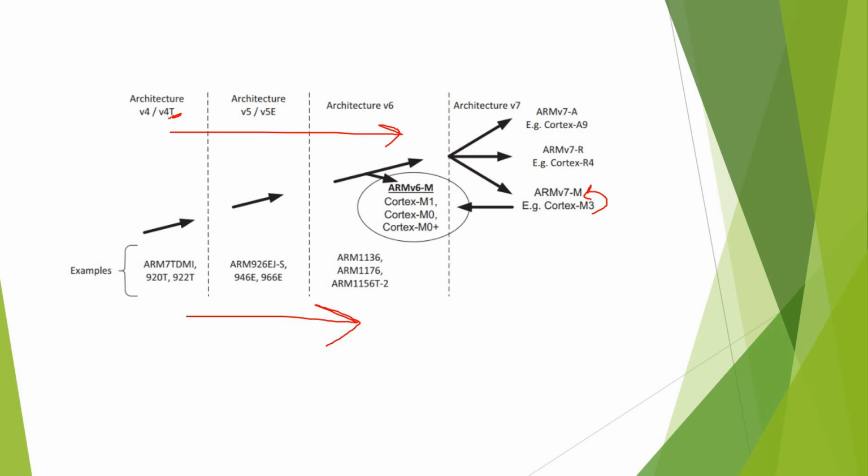This mix introduced new problems and challenges for ARM. One of the major problems was how the CPU will distinguish if the instruction will be 16-bit or 32-bit after doing a branch or jump. To solve this problem, ARM first introduced a new branch instruction called BX, or branch with exchange. Exchange means that the processor will have the capability, after a branch, to exchange its state to 16-bit or 32-bit execution flow.